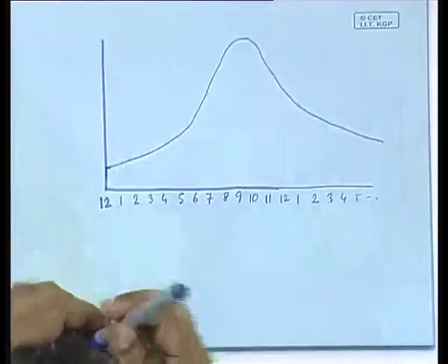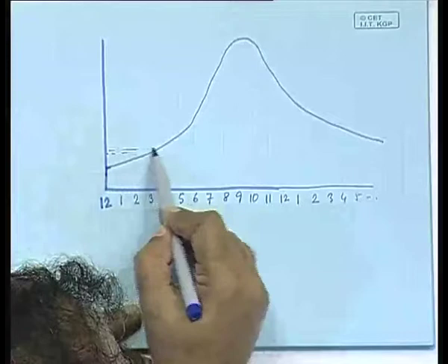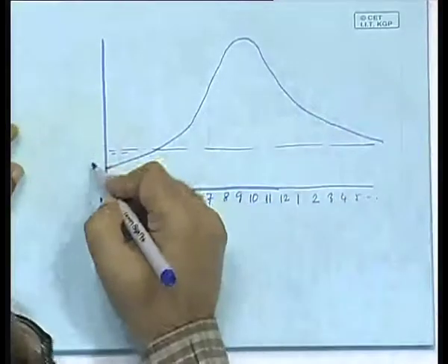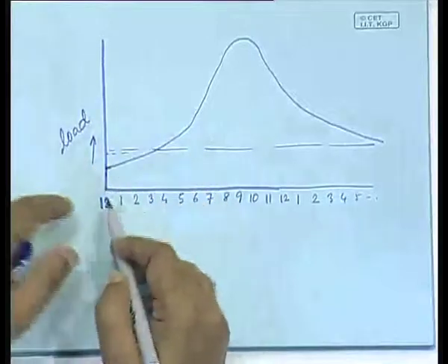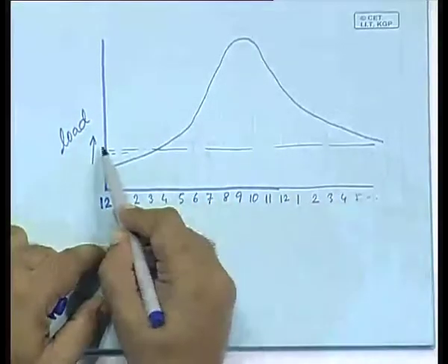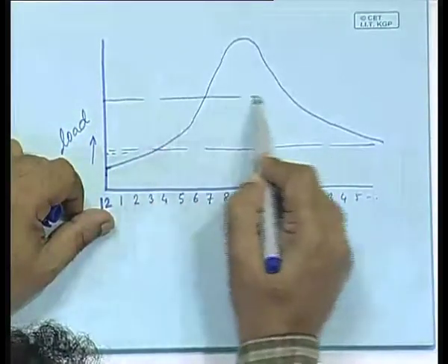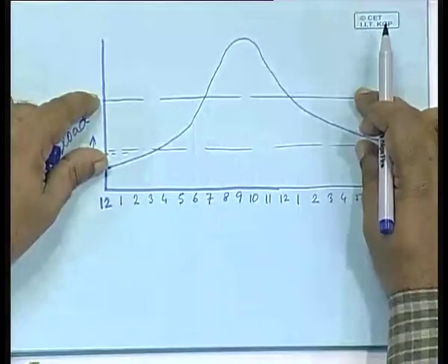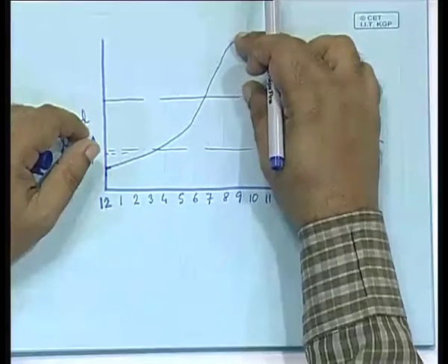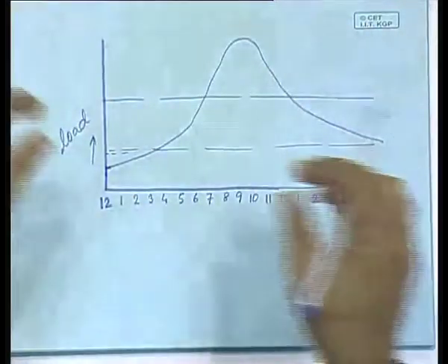So normally you would say that here is the amount of load, that means power demand, this is the base, right. So this is called the base load. About this is called the intermediate load, and about this is called the peak load. And peak load comes for a period of say 2 to 3 hours per day. Intermediate load comes more, and base load is always on. So that is the basic idea. In general, the large thermal power plants cater to the base load.